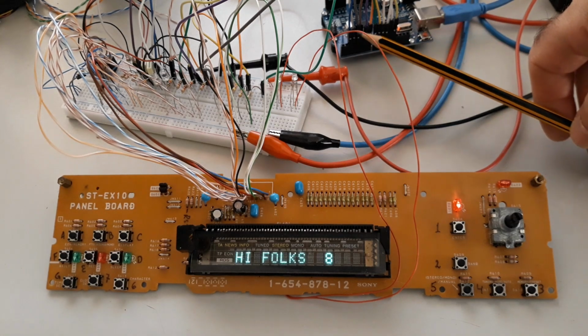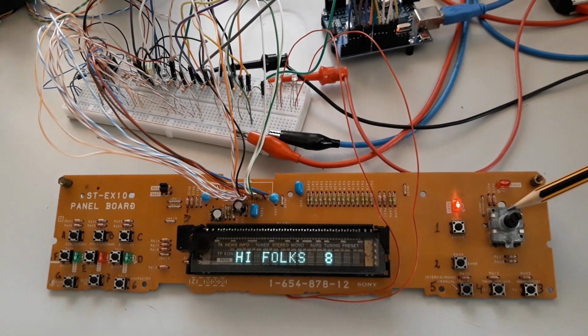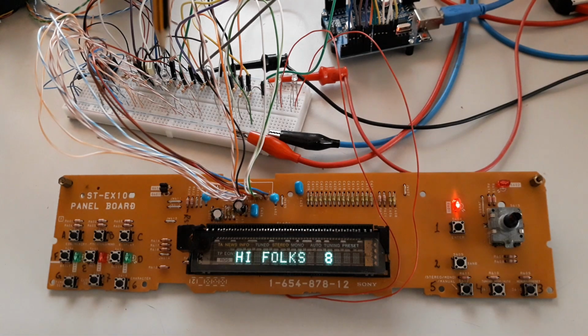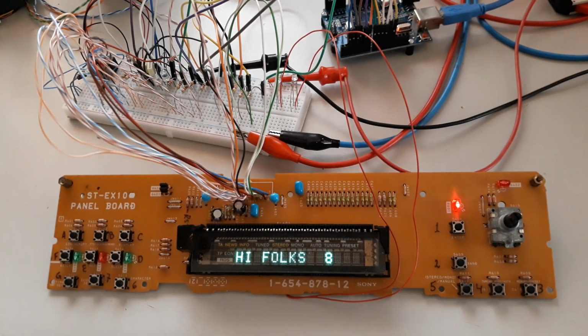After that we have pins 2 and 3 as the input of the Quadrature button, and 4, 5 and 6 as the control of the LEDs in the panel. Also, the analog pin A5 is used to control one LED in the panel, and A0 and A1 are used to read the status of the key lines.